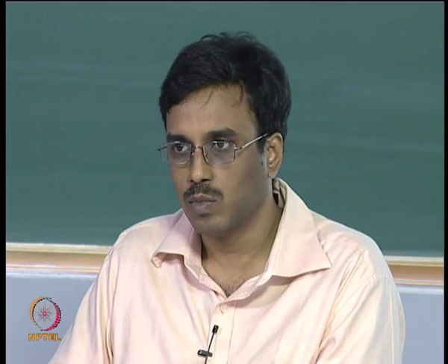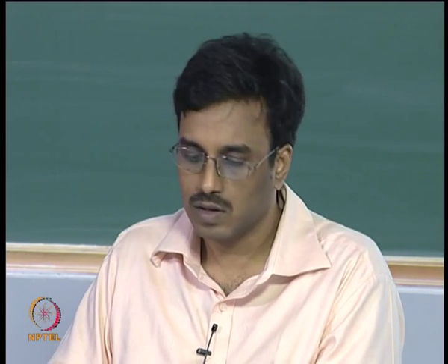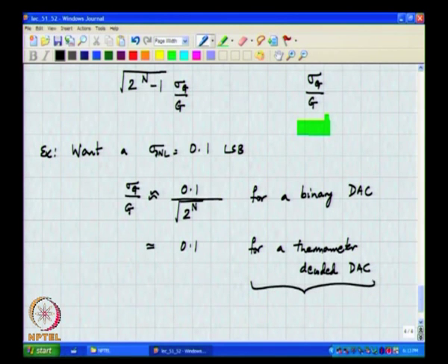What can you say about the INL? INL remains the same in both cases, all right. So, but what are we paying for in terms of a thermometer decoded DAC? Decoding logic.